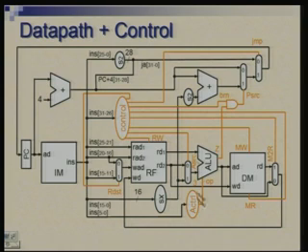But remember that ALU is being used for load store instructions also for a different purpose. So, we need to look at this also, but we don't need to feed all those 6 bits here. What we need to tell this circuit is which class of instruction it is, whether it is R class, one of those instructions, or it is load store or something else.